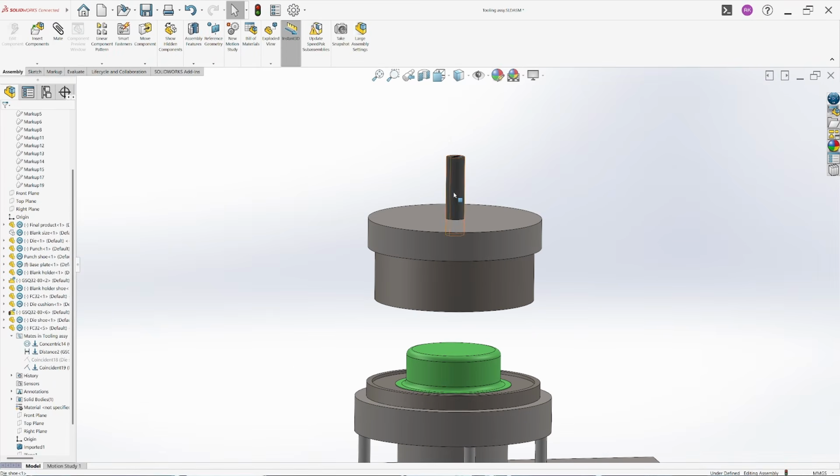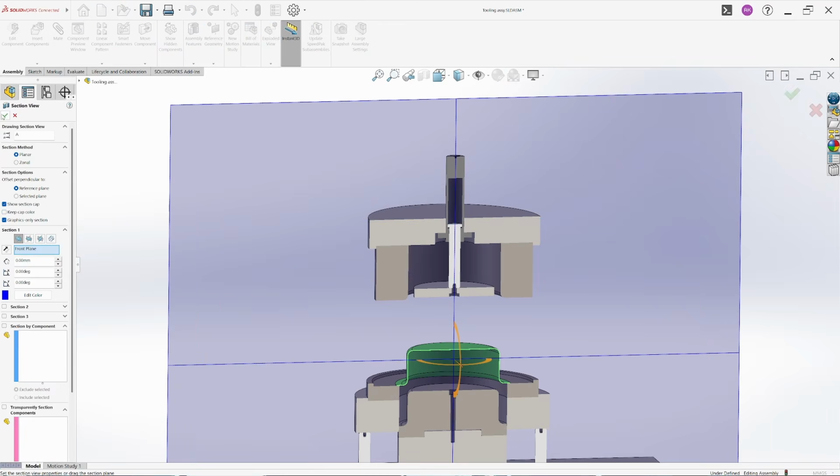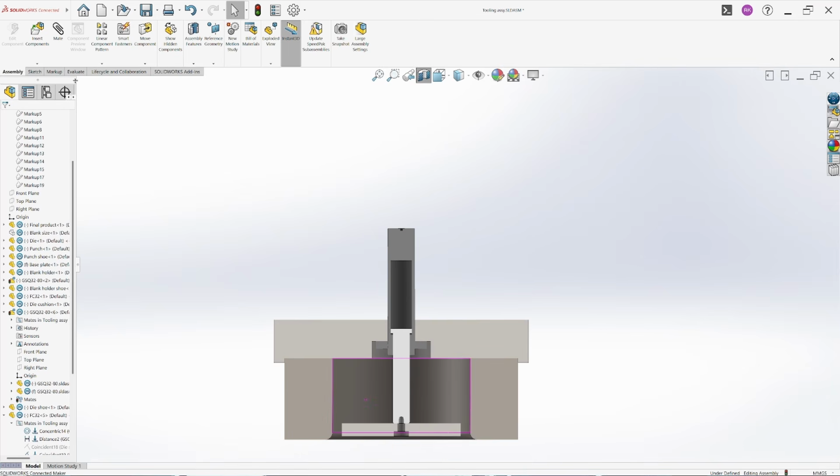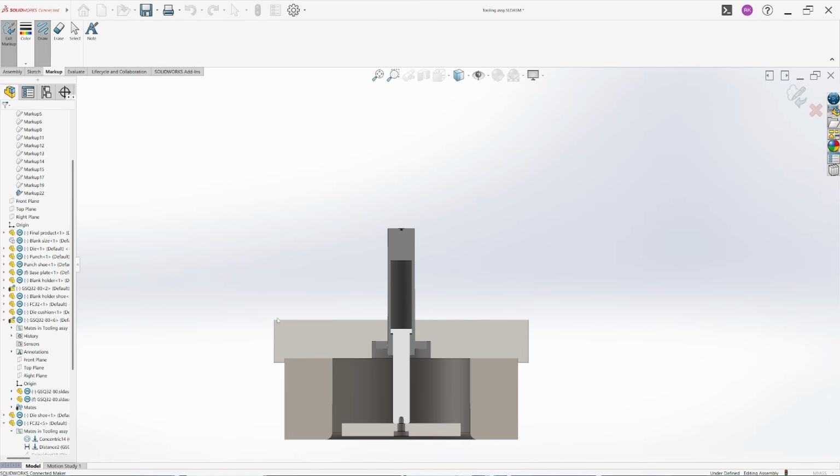Now how about this gas spring and how can we mount this over our pressing plate, right? We actually have many options, but let's discuss the first option. We can increase the height of this die shoe, something like this, and drill it for our gas spring.